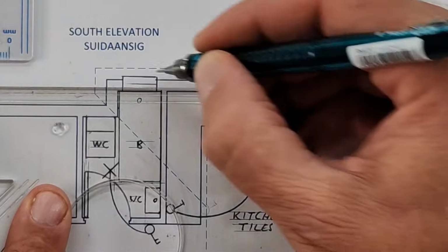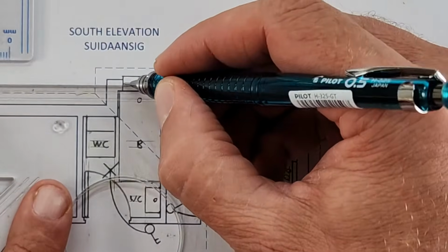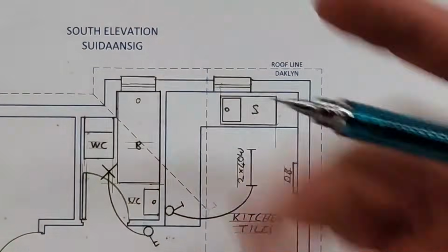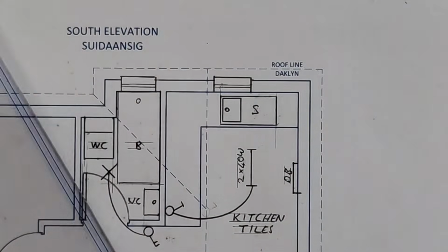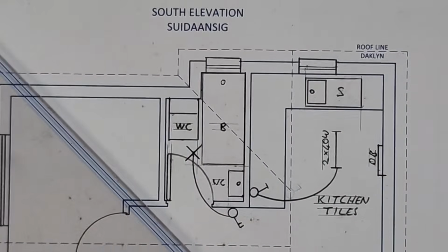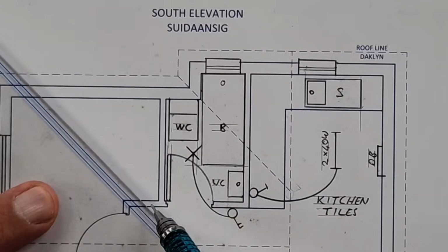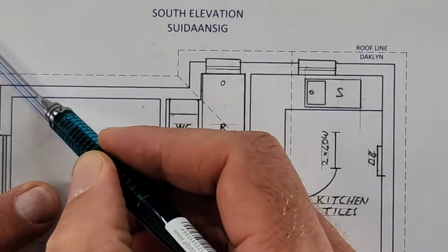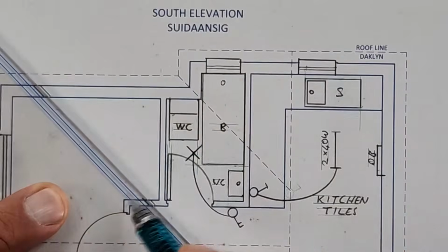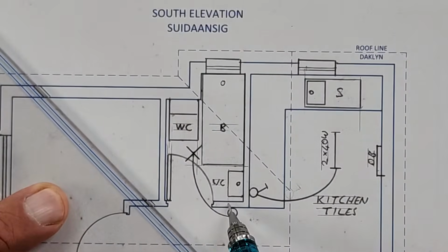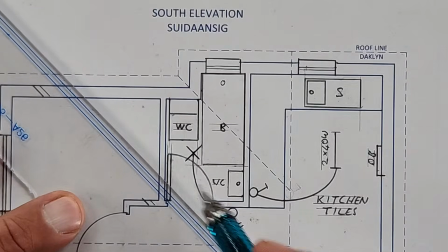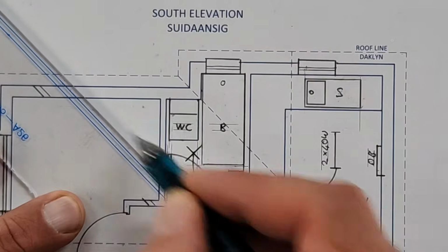Okay, when we do the hatching, this is civil hatching. Don't get confused between this and mechanical. So you can start from the one side and just continue. I'm just going to start. If you have a ruler like this, it's got plenty of scope for you. What's important with hatching is that your spacing allows you to cut through all the parts. So look here, I have to cut this wall as well. So I have to just plan myself that my spacing gives opportunity to do so.